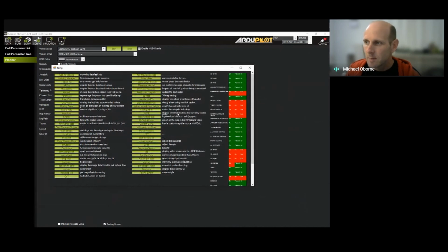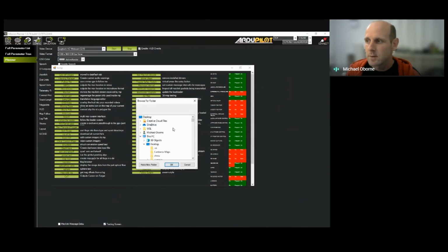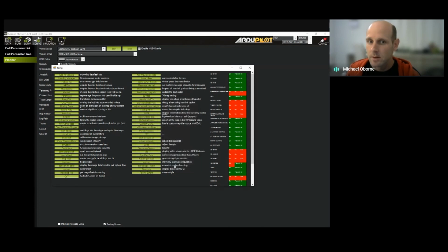So in here, there's two buttons that I'm going to show you. There's this DEM button, which stands for Digital Elevation Model. And then there's one called Custom GDAL, which loads a custom map source from GDAL. So what we're going to do is load the aerial photo using Custom GDAL. So I'm going to quickly browse to it, demo, and the path that I had before. I'm going to accept that. So that's loaded already.